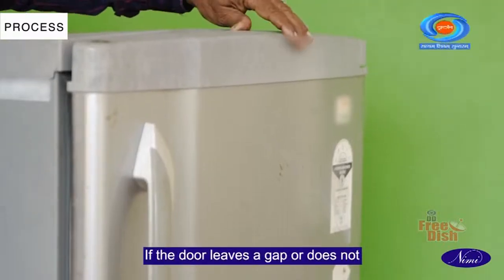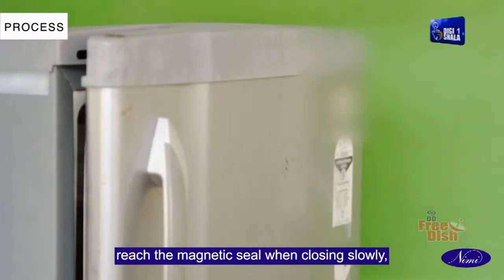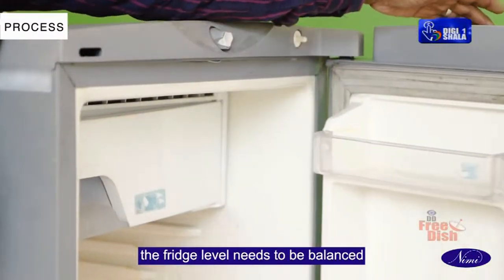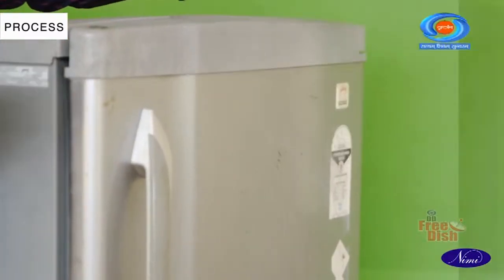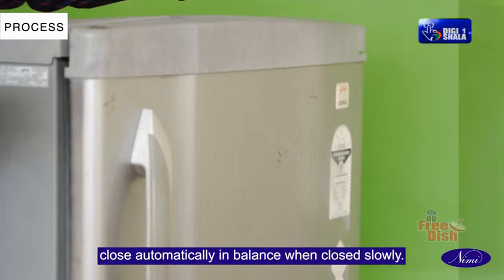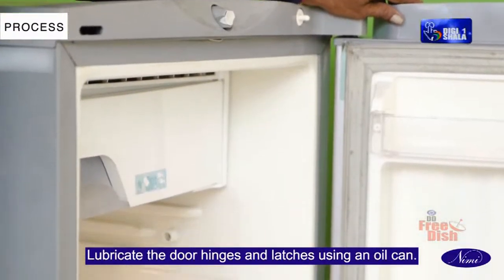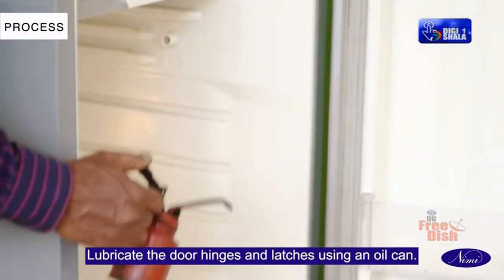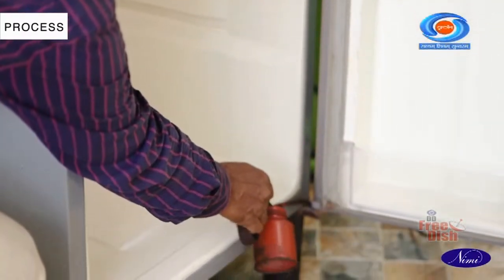If the door leaves a gap or does not reach the magnetic seal when closing slowly, the fridge level needs to be balanced for automatic closing. Adjust the bottom level screws to make the door close automatically in balance when closed slowly. Lubricate the door hinges and latches using an oil can. Then, settle the shelves in their proper places.